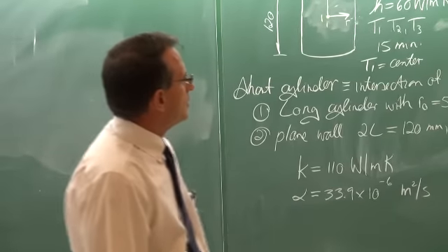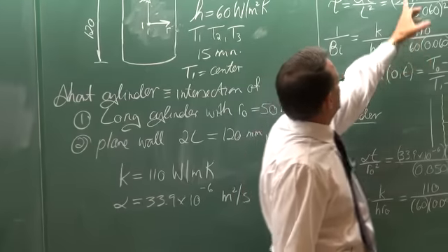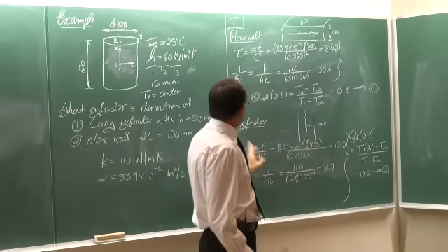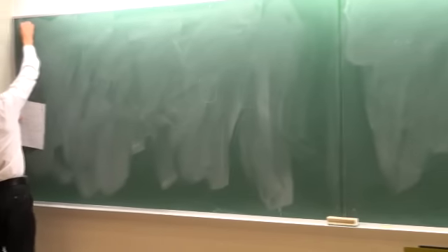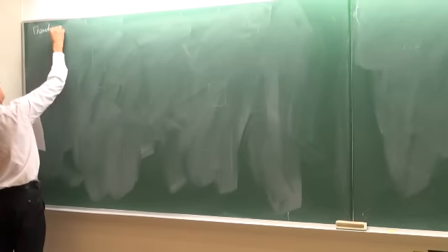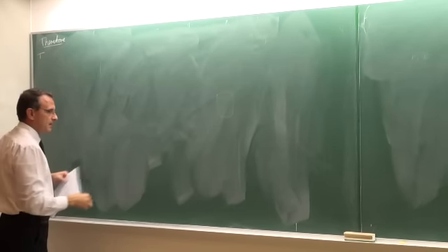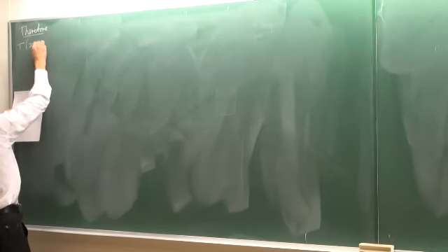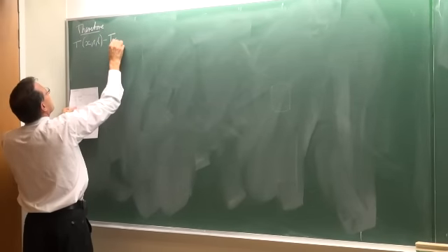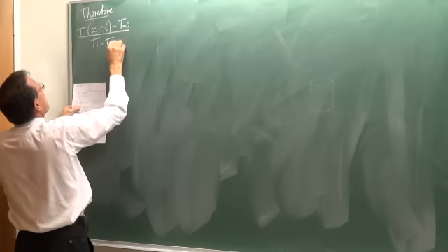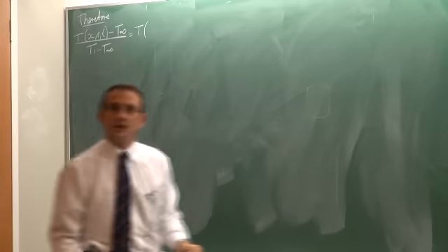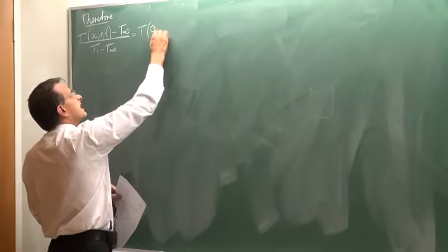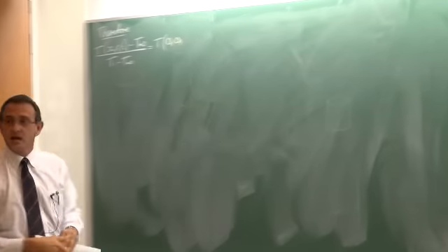So firstly, for the plane wall, we've calculated the non-dimensionalized temperature on that line. Then we do it for the cylinder, calculate it on that line, and now we put it together by saying that the temperature now, as a function of x, r, and t, is equal to the temperature where X is equal to 0, where R is equal to 0 also,